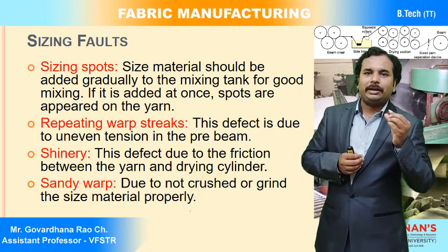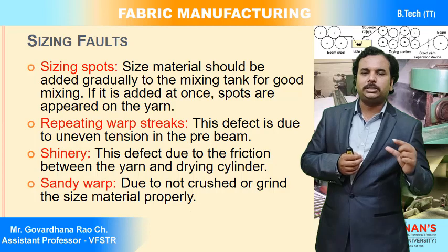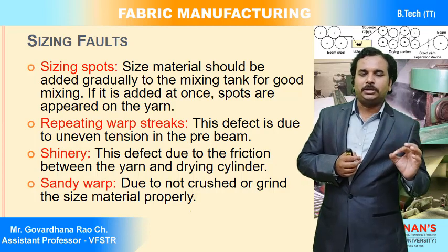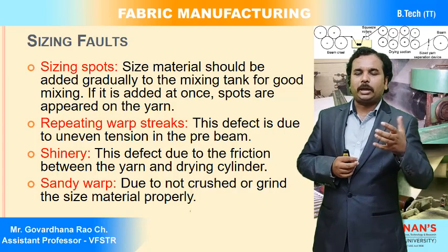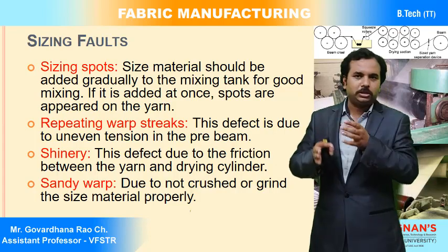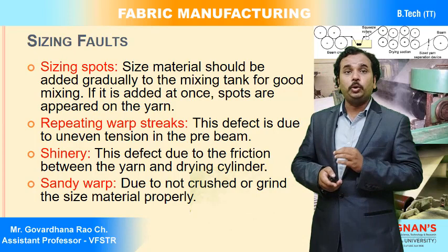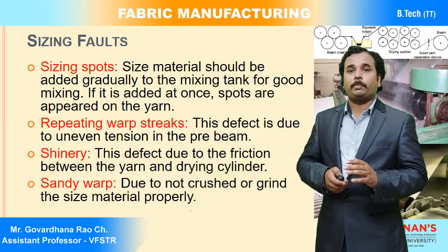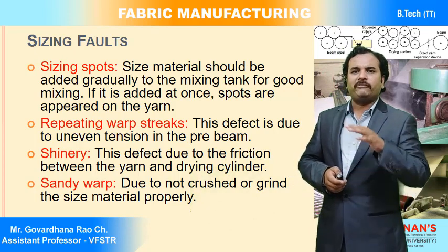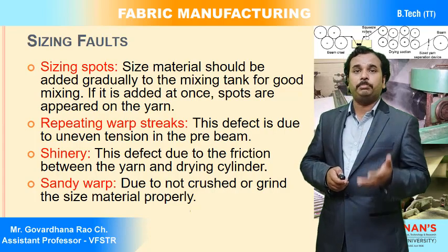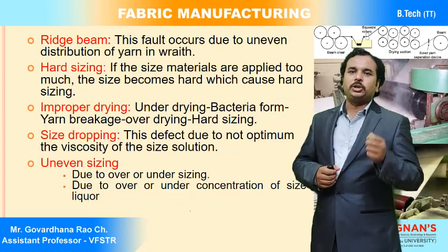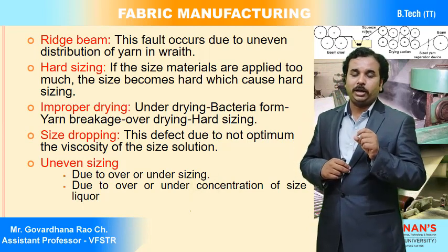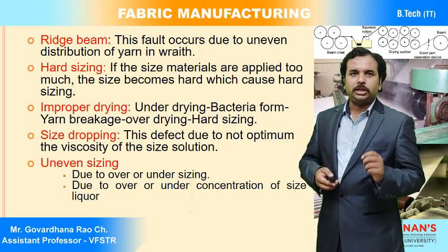So if you have granules with more diameter, it requires more time. If you do not give more time, these granules remain as they are and it is going to look like sandy warp. So the roughness of the warp sheet is going to be increased, and it should not be there. That is why the granule size is going to be maintained properly.